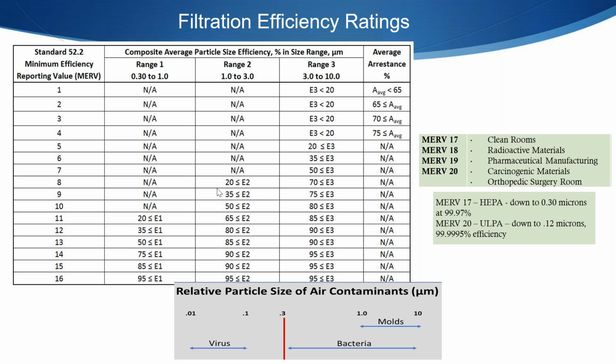A real advantage that we're seeing with alternate types of filtration and air treatment, airstream disinfection specifically, is the challenge that we have when we have those commercial rooftops, many of which are still operating. Kudos to the rooftop unit manufacturers, still operating decades down the road, and were designed specifically with the MERV 7, MERV 8 type filtration in mind. They don't have the space for higher levels of filtration, and they don't have the fan energy for higher levels of filtration. And so providing a means where you're not adding a significant amount of pressure drop. Most UV systems for airstream disinfection are 0.05 inches or less of pressure drop added. So it provides an alternate and supplemental means. It's not to replace filtration.